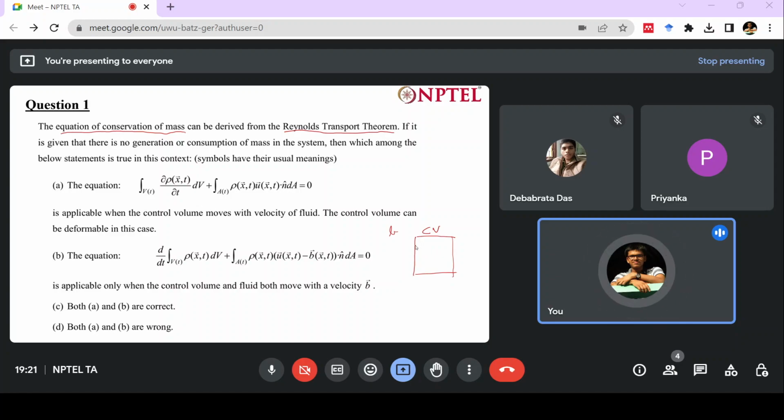In popular examples, like deriving the Navier-Stokes equations or the continuity equation, we generally shrink this control volume arbitrarily. Then we have a differential equation, since the volume can be arbitrarily small. But in general, Reynolds transport theorem will give us an integral equation.